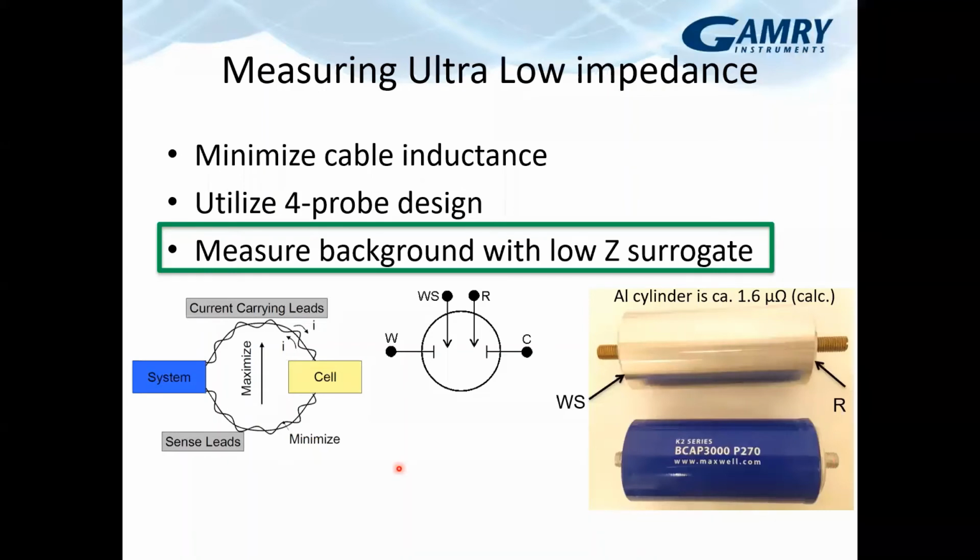I should note, it is important to note, these brass threads to that aluminum are going to have a contact resistance, and that is going to be measurable. We can mitigate that, and I did when this measurement was made, by putting our sense lead on the end of the aluminum, so we're not sensing the current transition from the brass into the aluminum, but we're sensing the end of the aluminum plate or bar on both sides.